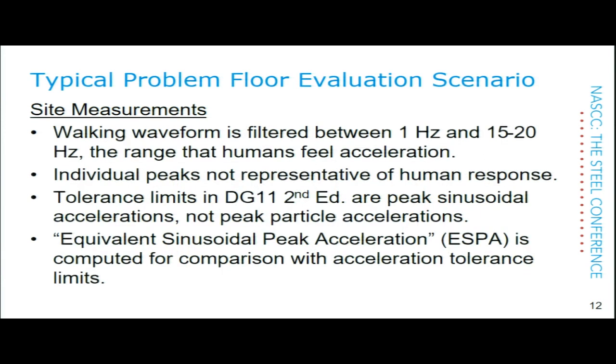filtered. And it's filtered between 1 and 15 to 20 hertz. Below 1 hertz is of no interest. We as humans are not sensitive to vibration frequencies above 15 or so hertz. So it's filtered to that range.